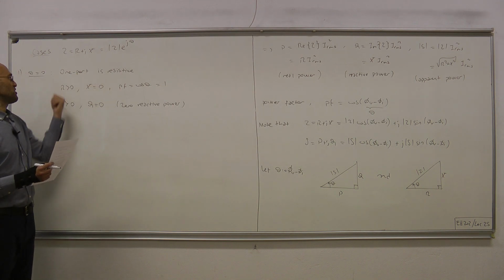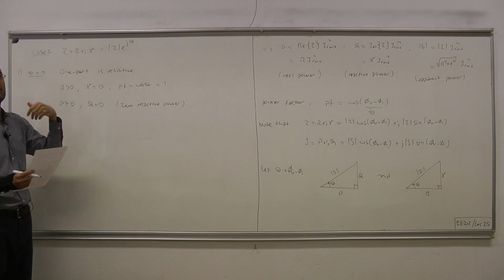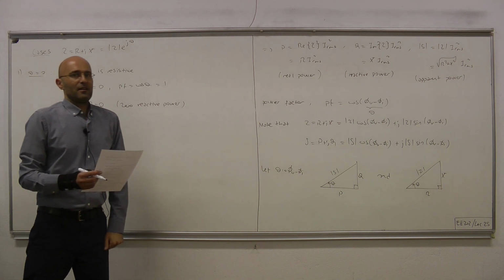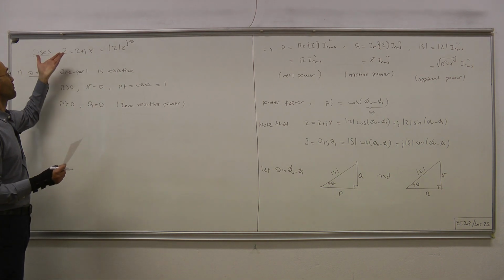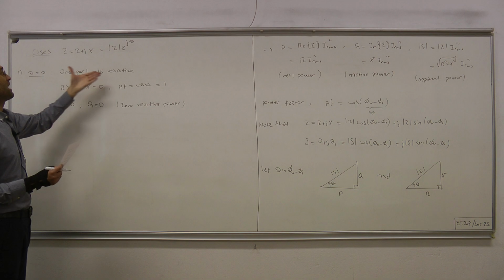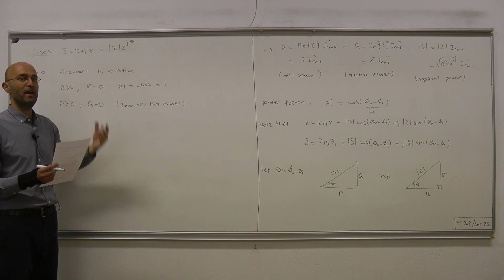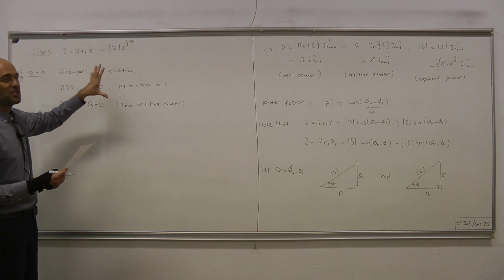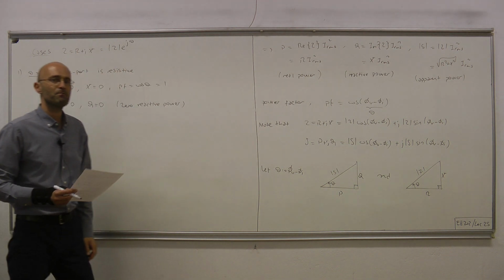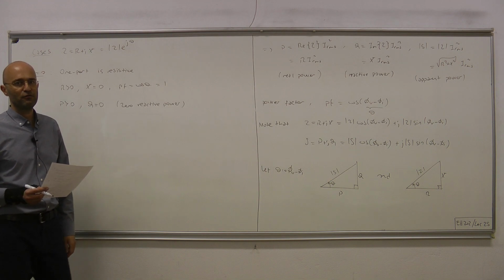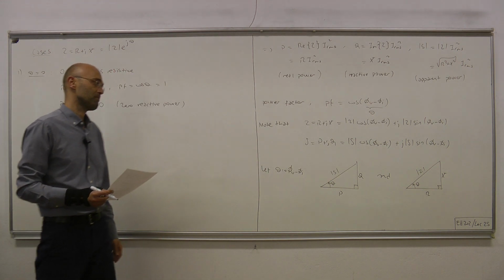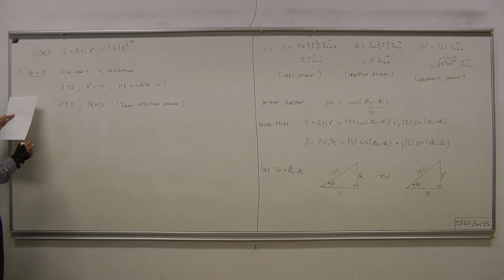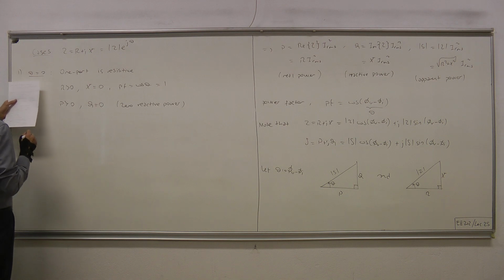Of course, since Z depends on the frequency, therefore its real and imaginary part depend on the frequency. At a different frequency, okay, it may not be resistive. This condition may break down. So we should always keep in mind that all these conclusions that we make are considering some particular frequency. Okay, let's say 50 Hertz, the usual frequency of the network. Okay, so that's the largest power factor case.